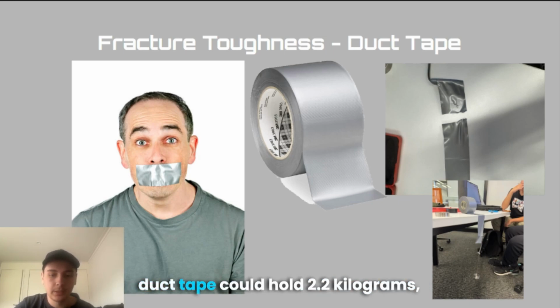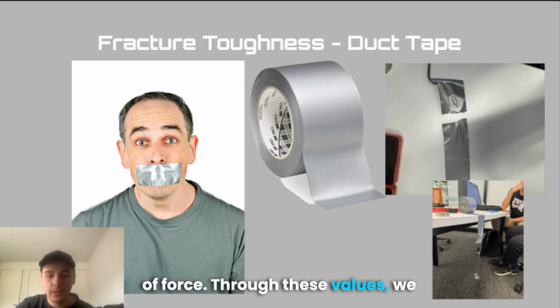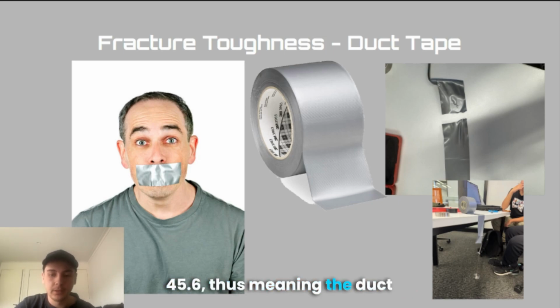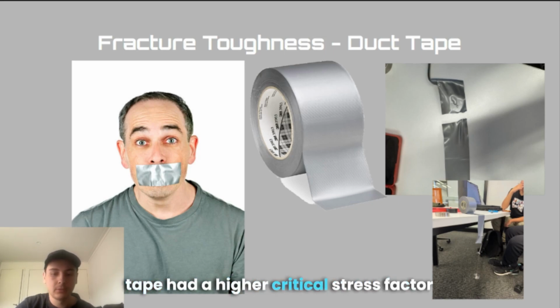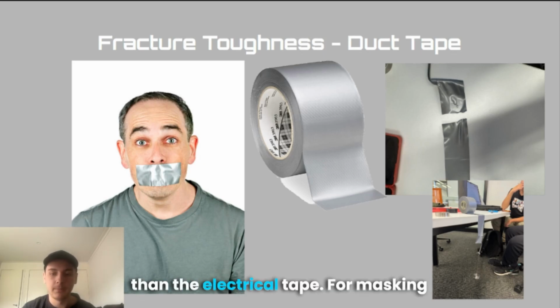During the test, the duct tape could hold 2.2 kilograms, meaning it held 21.582 newtons of force. Through these values, we developed a K1C value of 45.6, thus meaning the duct tape had a higher critical stress intensity factor than the electrical tape.